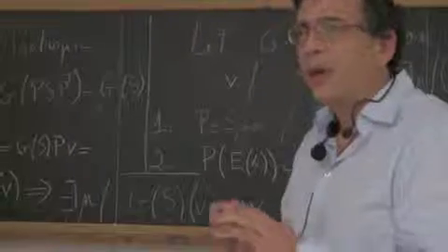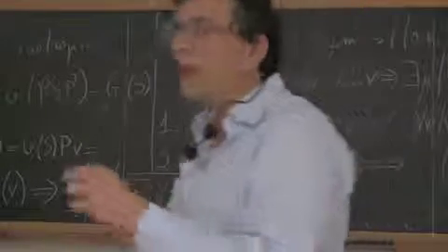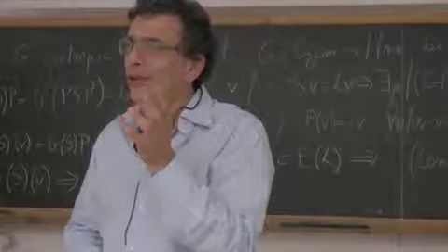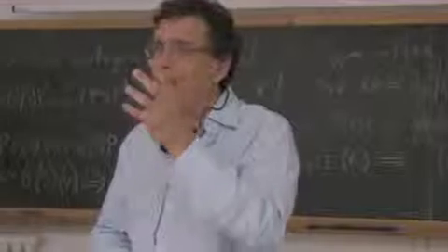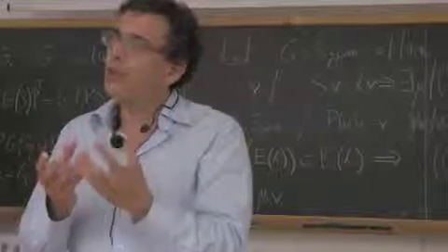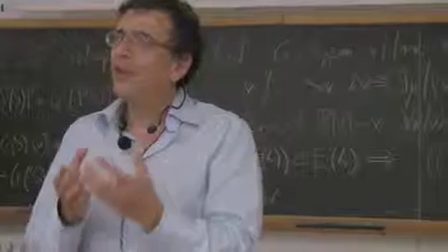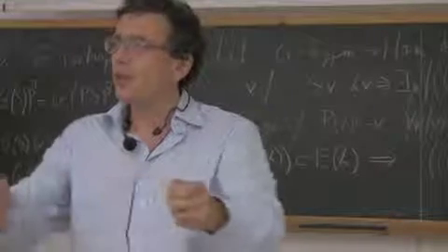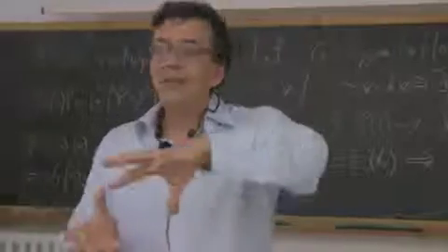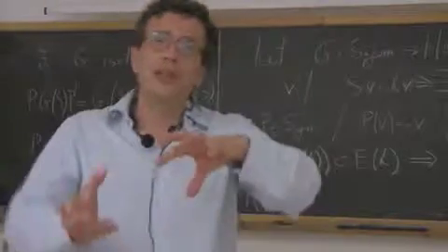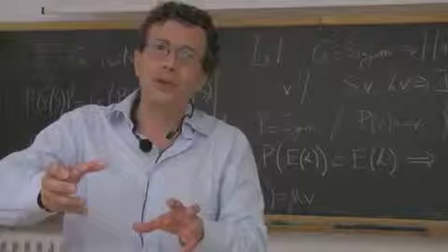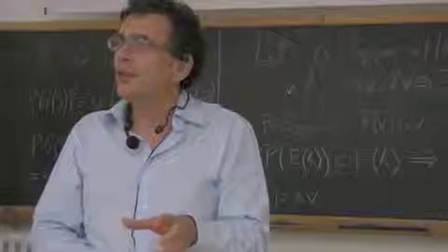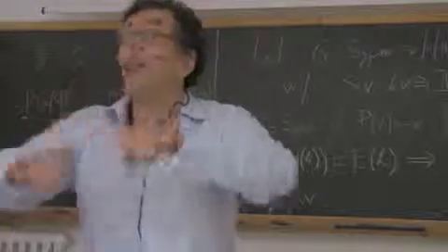Okay, so when you say that a body has no preferred directions, mathematically you say the constitutive equation verifies this property. If you turn the reference configuration and you deform, Piola stress is turned exactly of the same amount in which you have turned the reference configuration. And this is true for every rotation.